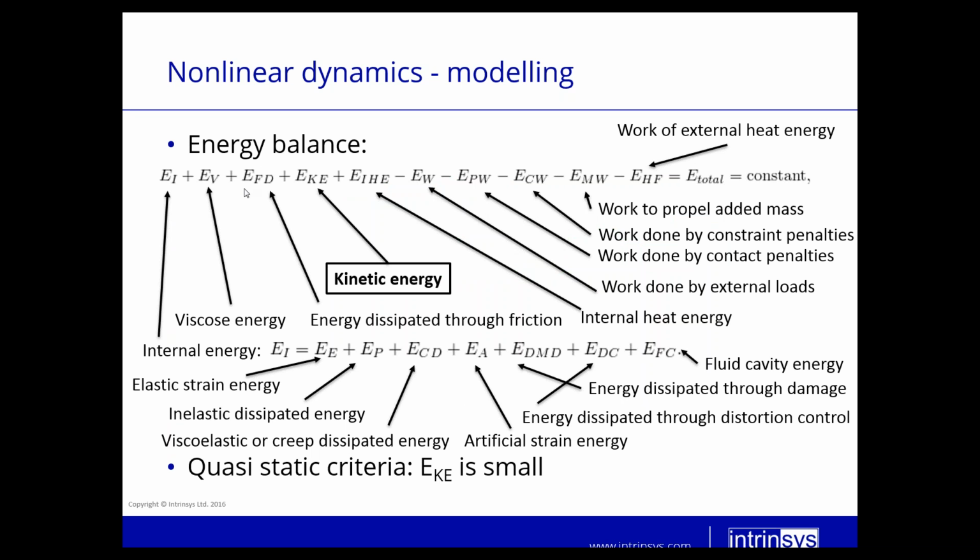So how can you check that? First of all, you have to check your energy balance. It's a fairly long equation, but what this means is in your simulation, your total energy throughout the simulation has to be constant. Now, due to round-off errors and all that, it's usually within 1% of its actual value throughout the simulation, but generally it shouldn't change. So that means whatever energies you put in, they can only convert from one to the other.